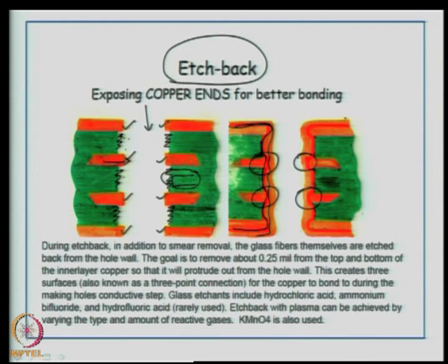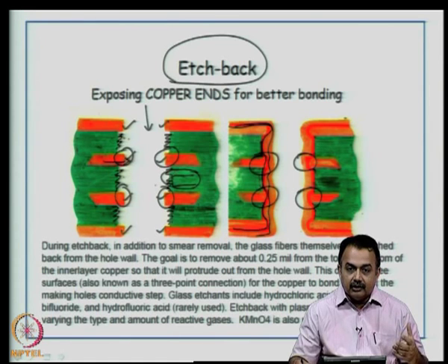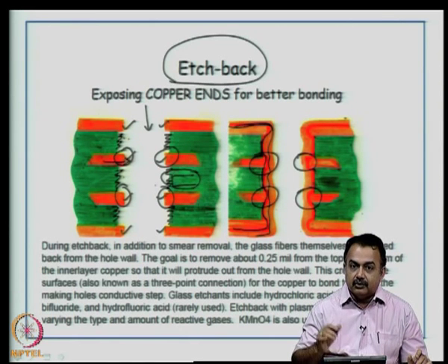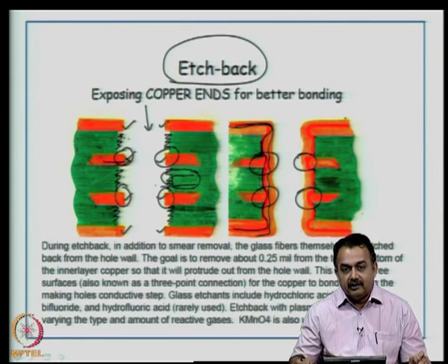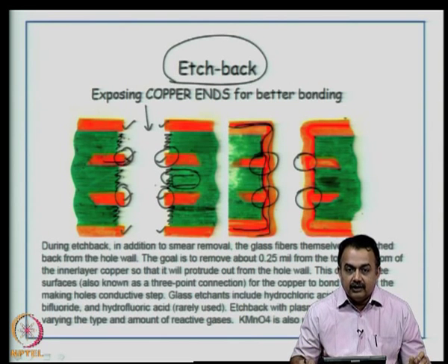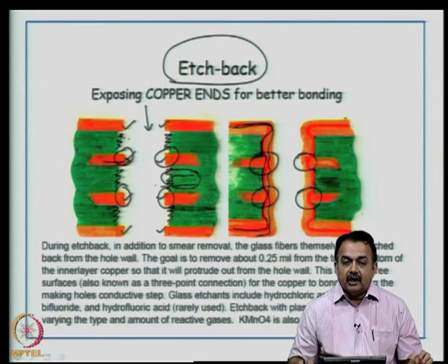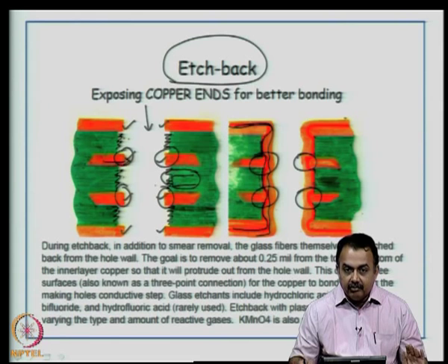So, you get these kind of pillars, and we call this a 3-point connection, and this will ensure copper to dielectric bond as well as the three types of copper existing at this point to be reliable, and it can undergo thermal cycling very efficiently without any breakage. It can withstand all mechanical failures, vibrational failures or vibrational effects.